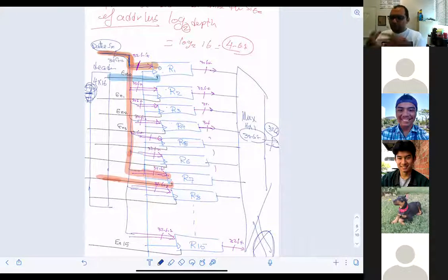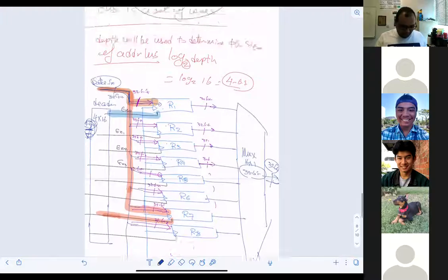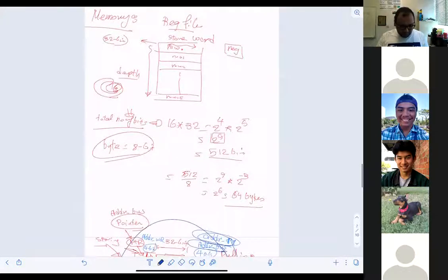We defined the pros and cons for each one, and we said all of them are still valid. They can be used for different applications. We picked one of them, which is basically PIPO, and we built something acting as a memory with an associated combinational circuit, defining the size of the memory by the depth and the number of words, which is the number of flip-flops per element on the row.